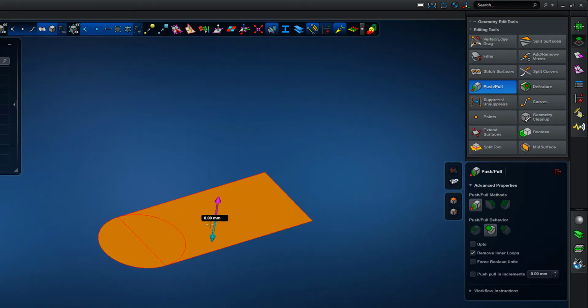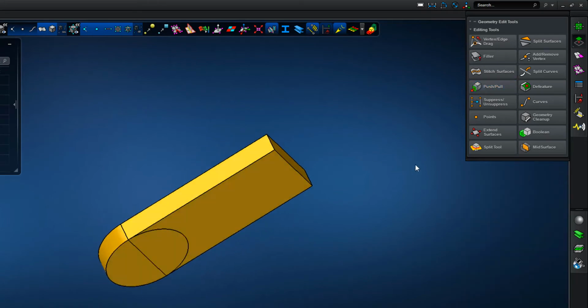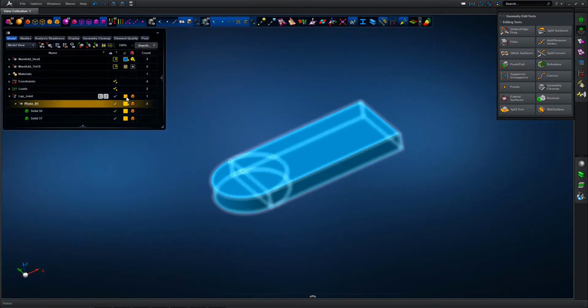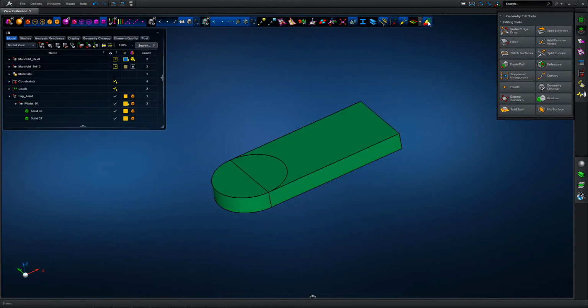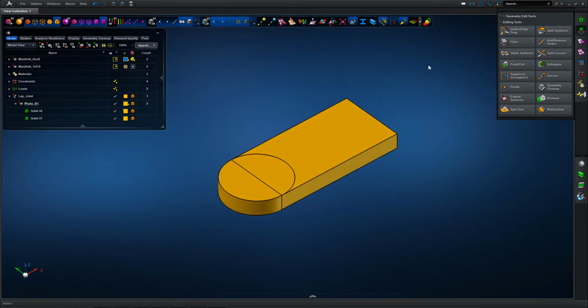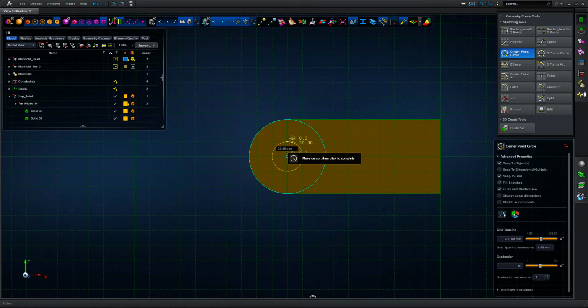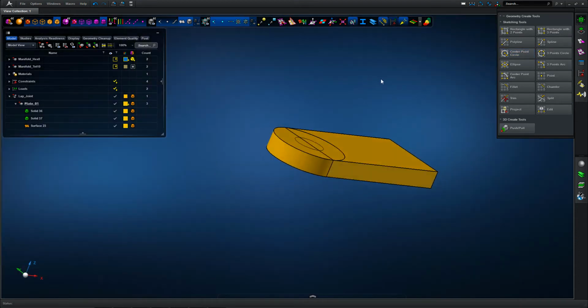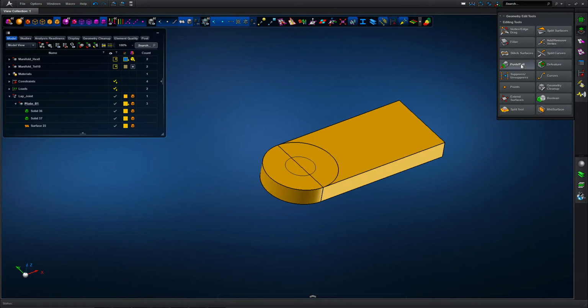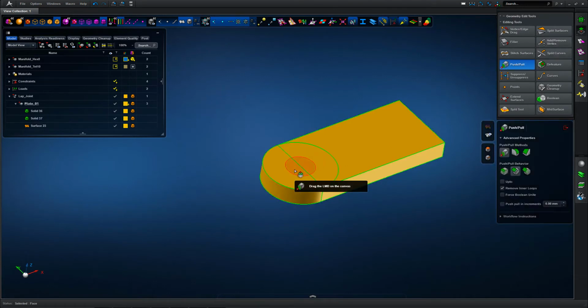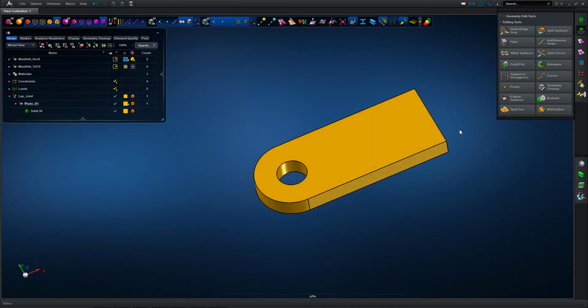Some of the simple sketcher surfaces can be extruded up into the third dimension to give us a piece of solid geometry, and you can see in the tree the solids defined. We have the concept of mappable geometry, so whether we can map geometry for resultant hex meshing. We can set the color, and if the object is green we can hex mesh. If it's red we can't. So it's all about controlling the geometry to give us an assembly or definition that can be hex meshed as required.